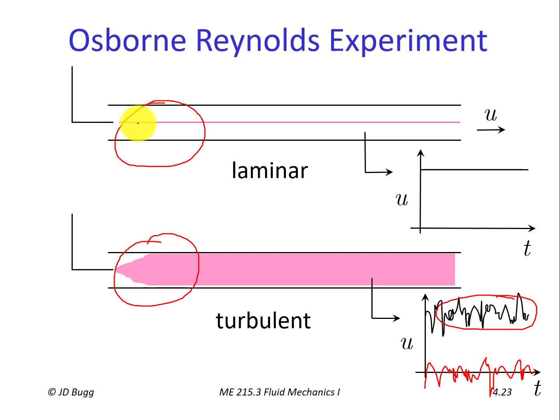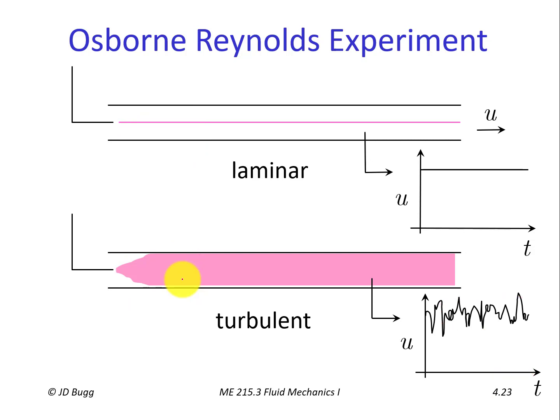Now, when you do this in the lab, you will notice that this distinct stream of dye does get smeared a little bit as you go downstream, but that's just diffusion. It's not fluctuations in the velocity of the water that's doing that. The dye is just diffusing out into the surrounding water slowly. This turbulent mixing is happening much, much quicker than that molecular diffusion could possibly happen.